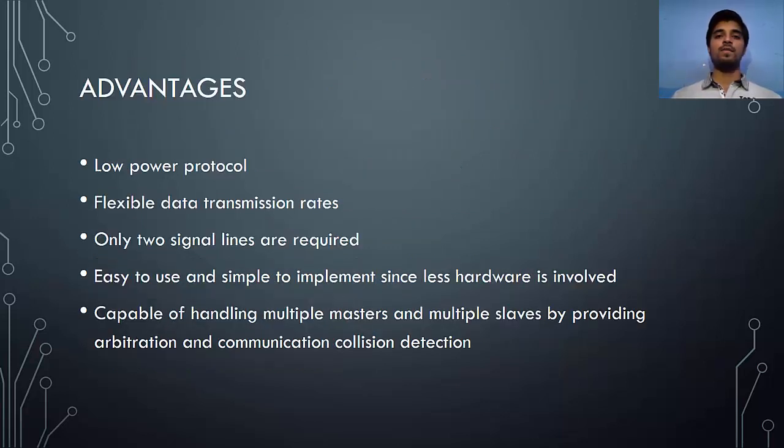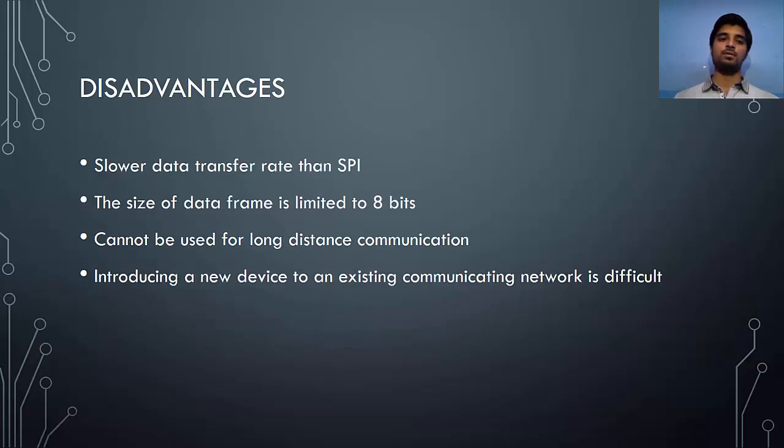Now let's see the advantages of I2C protocol. The biggest advantage is it is a low power protocol. Flexible data transmission rates. Only 2 signal lines are required. Easy to use and simple to implement since less hardware is involved. Capable of handling multiple masters and multiple slaves by providing arbitration and communication collision detection.